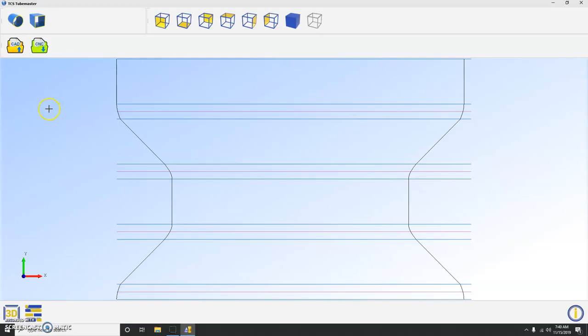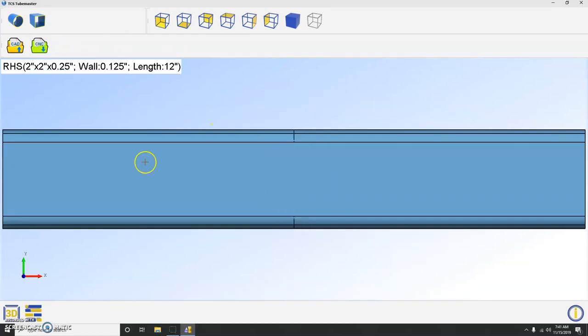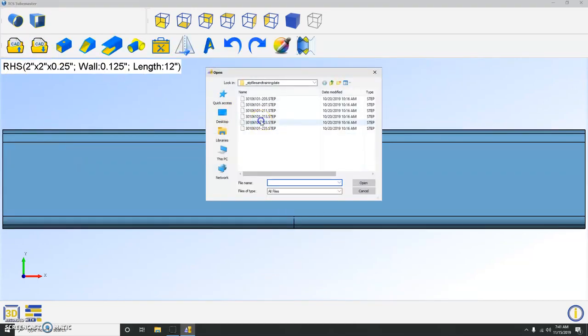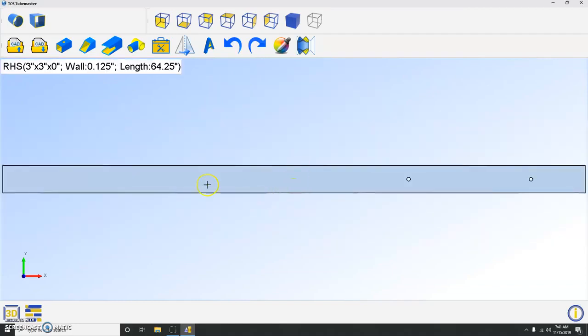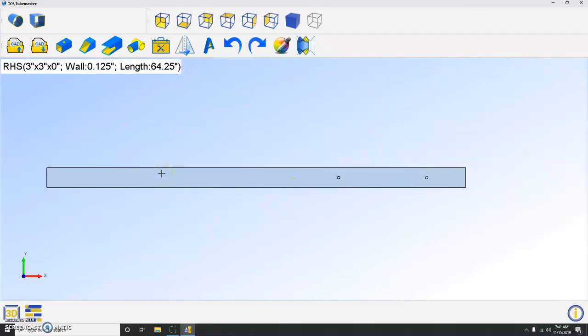Right? Now you can go all the way back. It's saved, so the flat pattern is done. So you could go back and do some more conversational. You could go back here and import some more, however methods you want to work. So you could go and create a lot of different parts. You don't have to create a part and then go and generate G-code. You do need to create a part and generate a flat pattern.